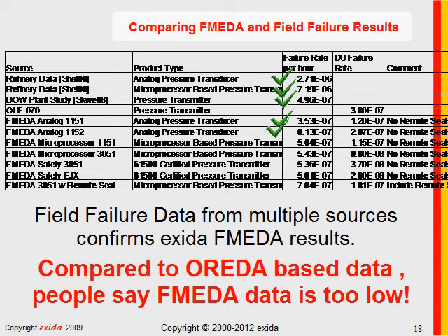In fact, when you include remote seals, even FMEDA results start coming up in value, of course. And that's one advantage of FMEDAs. There are absolutely separate failure rate numbers for impulse lines and remote seals and all the other accessories that go with a pressure transmitter.